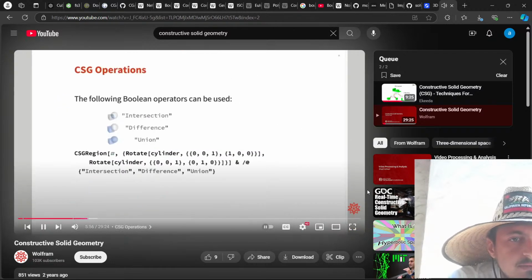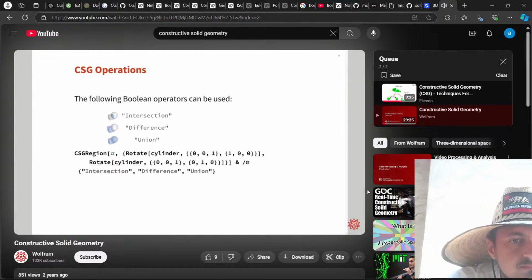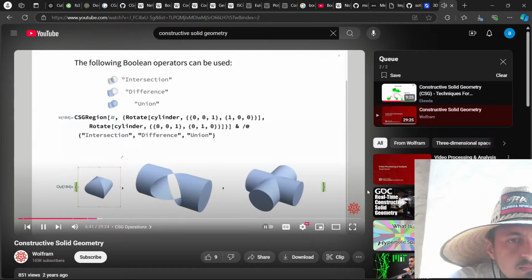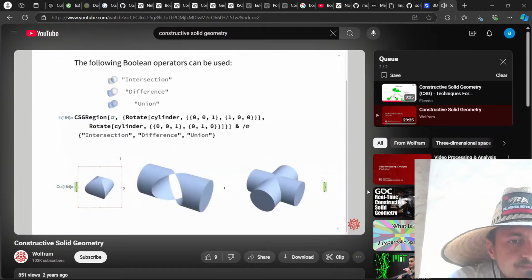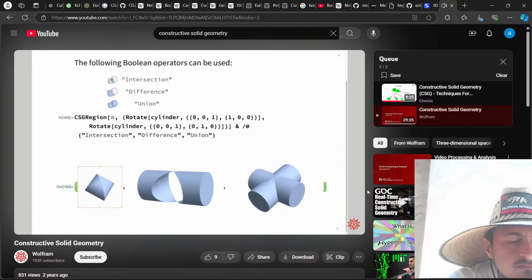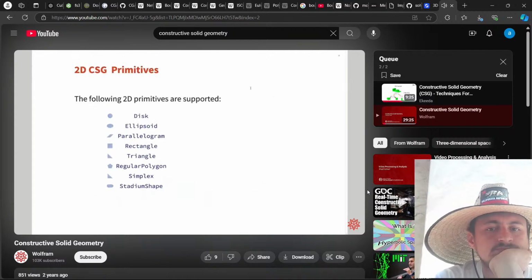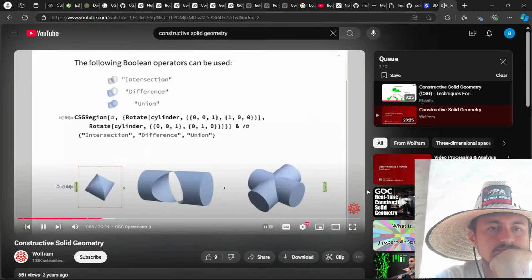So now if you look at the list of operations, you also start with no point. We actually analyze this. So this is the intersection of the cylinders. Actually, I have 2 cylinders here, sorry. So you have the result here. This is the difference, and this is the union of the 2 cylinders. So you see that you can easily capture the intent of your design. You want to join them, you want to make a difference, and such.